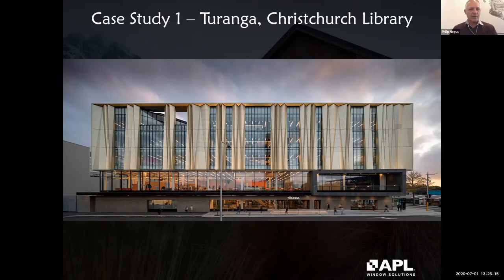I don't know if you can pick it up on this particular image, but on the first level glazing, you can see the vertical white columns. They're actually still quite white, whereas the spandrel panels in the 3 floors above are quite green, and that's due to the triple layered silver coating that they have on the low E on those upper 3 levels. Obviously, it gives a bit of a tint. There was a real focus on energy efficiency in this building due to the large expanses of glass.